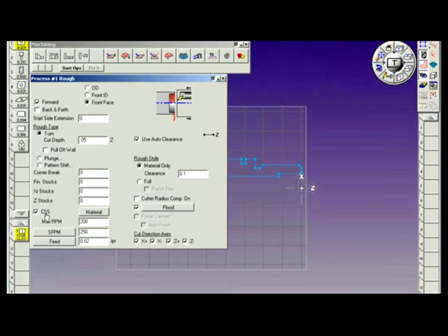CSS starts the cut and increases the RPMs as the tool moves closer to center, maintaining the same metal removal rate. CSS is programmed by giving it a cap or a limit, a not to exceed. I'm going to give it a not to exceed 3,500 RPMs. This is typically shown in the code as a G50 command before the G96.